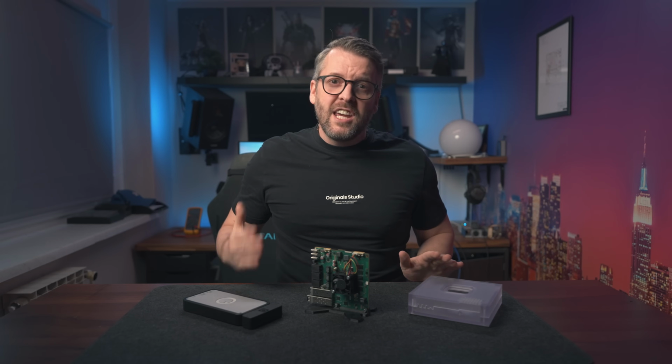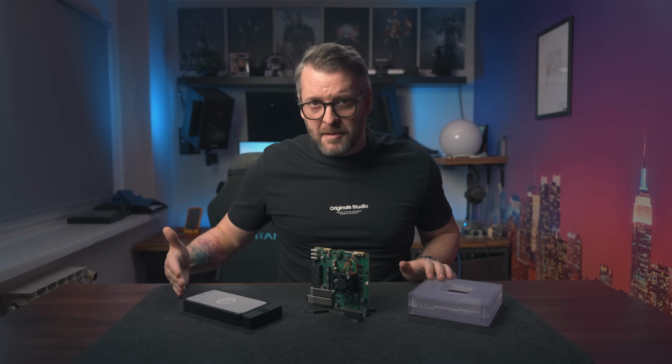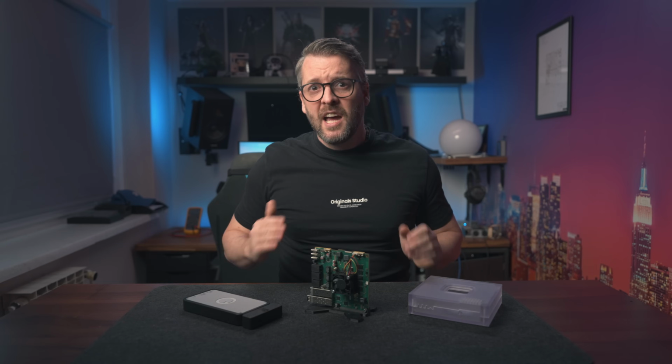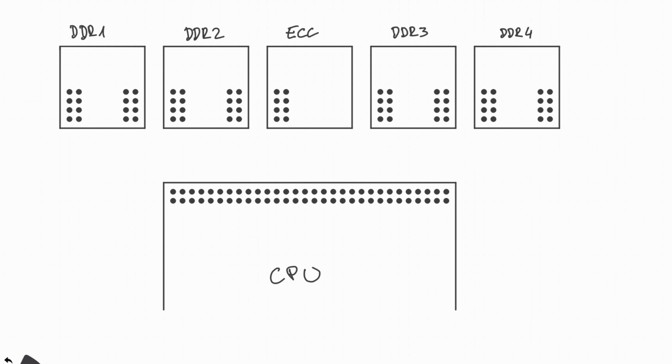This means that each RAM die has 16 data pins, and because the CPU has 72 of the matching pins, this means we can connect up to 4 RAM chips for a total of 64-bit wide bus, or, because we're running ECC in our case, 72-bit wide bus.